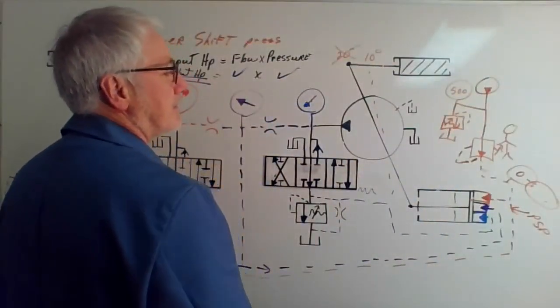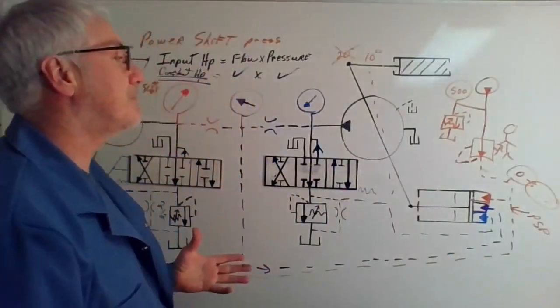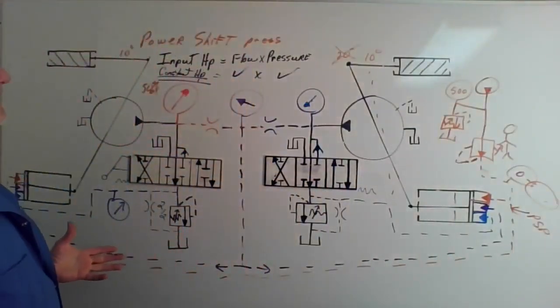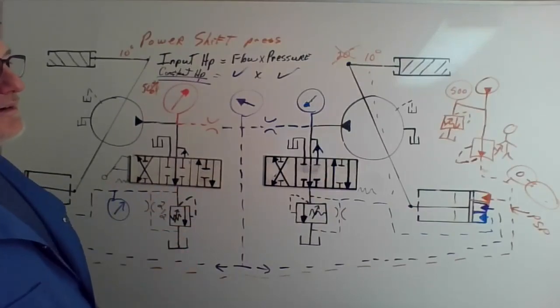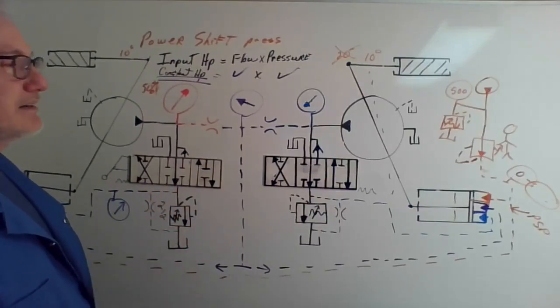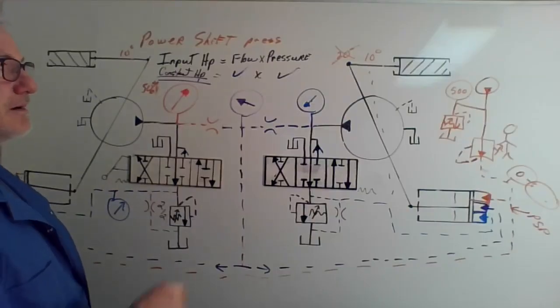And I just want to be clear that it is operator input. And the beautiful thing about this operator input is that if we know you're only going to use 50% of its hydraulic capabilities, then why wouldn't we connect that to the engine control? And so now we can turn down the engine speed finally. So we don't start by turning down the engine speed, we finish by turning down the engine speed.